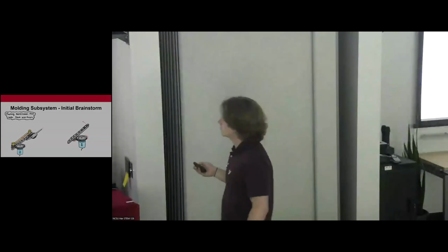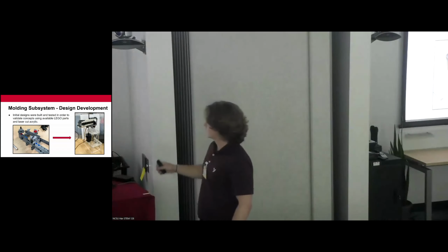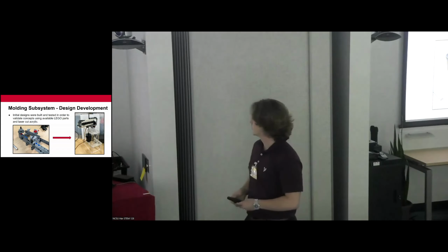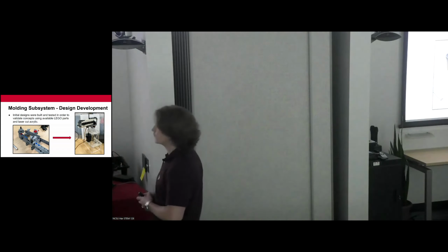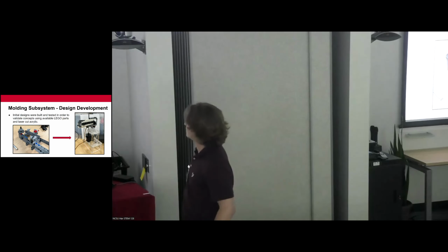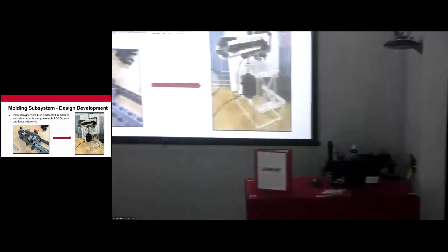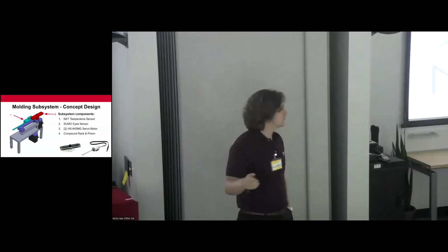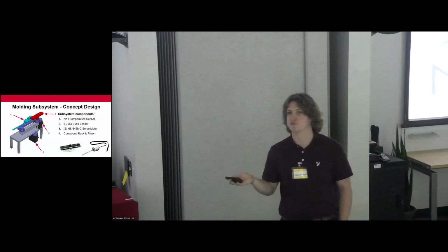That's where our brainstorming led us. We started to try to build this with some of the Legos they mentioned earlier. On the left is a very crude early construction of this, where we have these gears driving something from a rotational motion and actually making it move forward. And then I think one night, Will went crazy and actually built the entire thing out of Legos. No idea how long that took, but this early prototype definitely helped us a lot. It really validated that this concept could work, that we could rotate and extend linearly using the same form of motion. Following this early design development, we were able to reach this concept review, where we decided we needed a temperature sensor, something to actually see which of these 3 ovens are here at any given time, and then 2 servos to accomplish each of those types of motion.